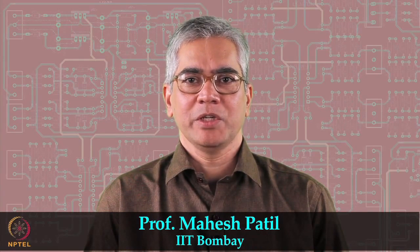In this lecture, we will look at a precision half-wave rectifier in which the op-amp does not enter the saturation region. We will then see how a precision full-wave rectifier circuit can be made up using the circuit blocks we have already seen. Finally, we will look at wave shaping using diodes and how to use it to convert a triangular input voltage to a sinusoidal output voltage. Okay, let us get started.